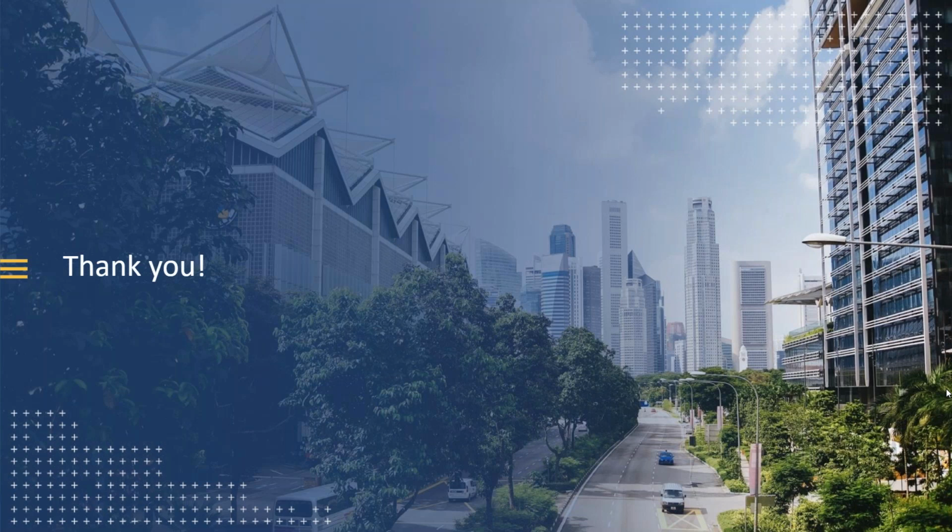It happens very regularly, every month or two, with new systems added. But definitely you can define your own local coordinate system that you would like to work with. You just need the coordinate system parameters, the projection parameters, and you define your own. It's a part of TBC.